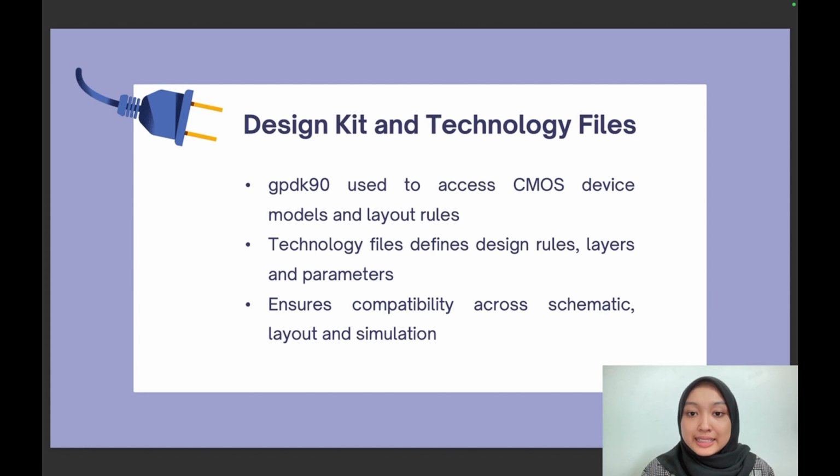So these are the design kit and technology files involved in this assignment. GPDK90 is used to access CMOS device models and layout rules. Next, technology files define design rules, layers and parameters. And last one, they ensure compatibility across schematic, layout and simulation.